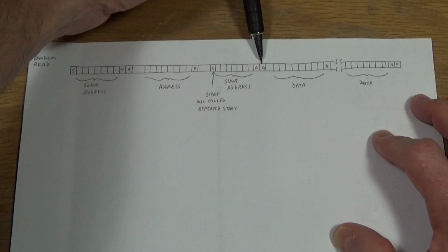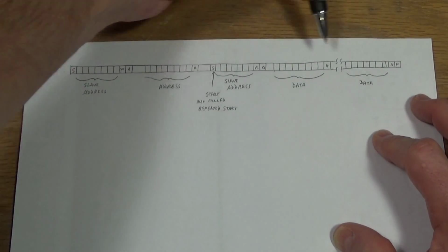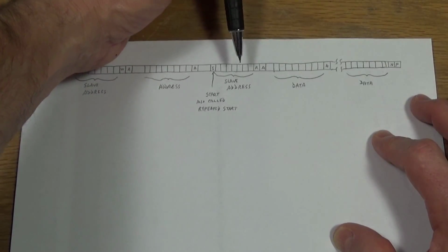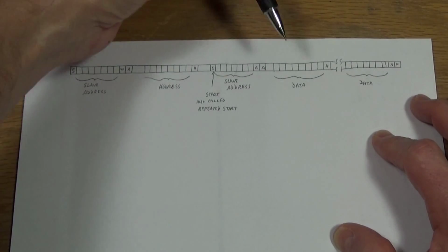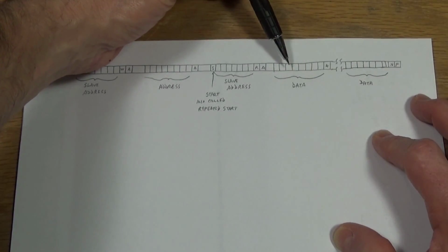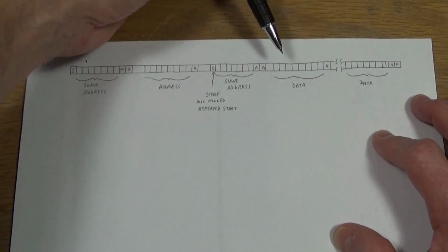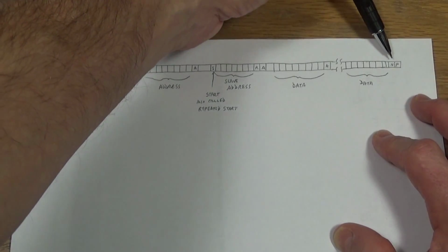In this case it's a read instead of a write, so the 8th bit will be high. It waits for the acknowledge from the slave, and then it starts reading the data in 1 byte at a time for as long as it keeps clocking. And remember, I said that the address pointer in the slave increments each time. So I can read a whole bunch of data from the device all in one go with this one stream. When the master is finished reading, it sends a not acknowledge.